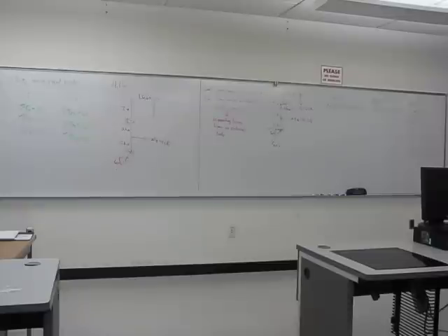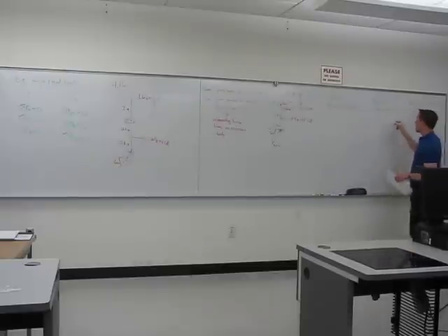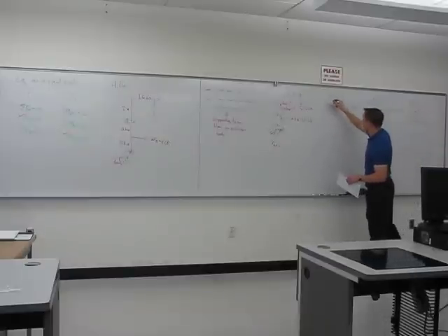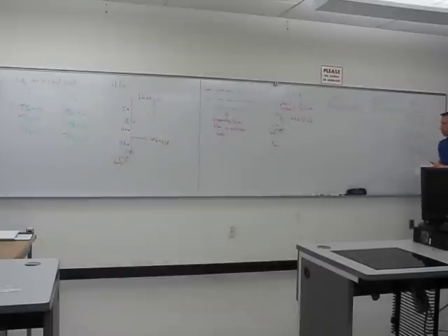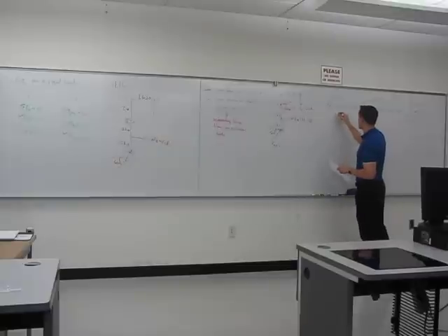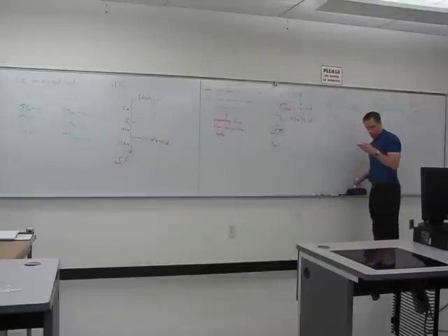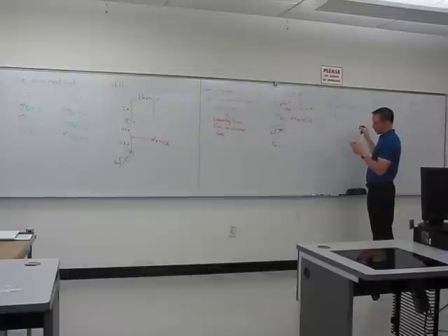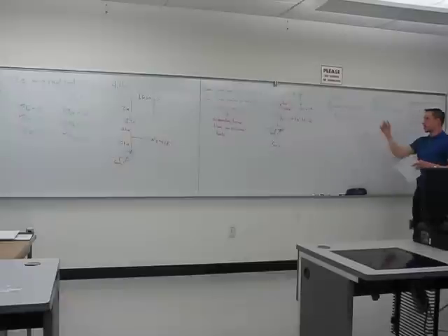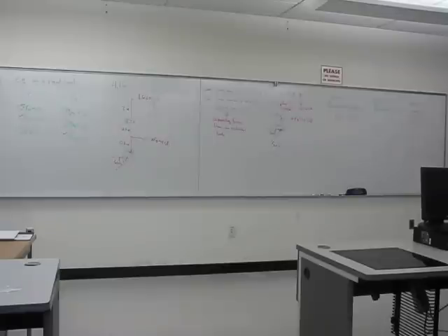Now that we know FA is equal to 8, so this 8 right here, we can drop that in right here and right here. And then plug in the FB and FD that were given, and we can solve for FCX and FCY. So FCX, that one turns out to be negative 8 pounds. So that means the x component is really acting to the left. I guess to the right, I got a negative number. That just tells me in reality the x component is to the left.